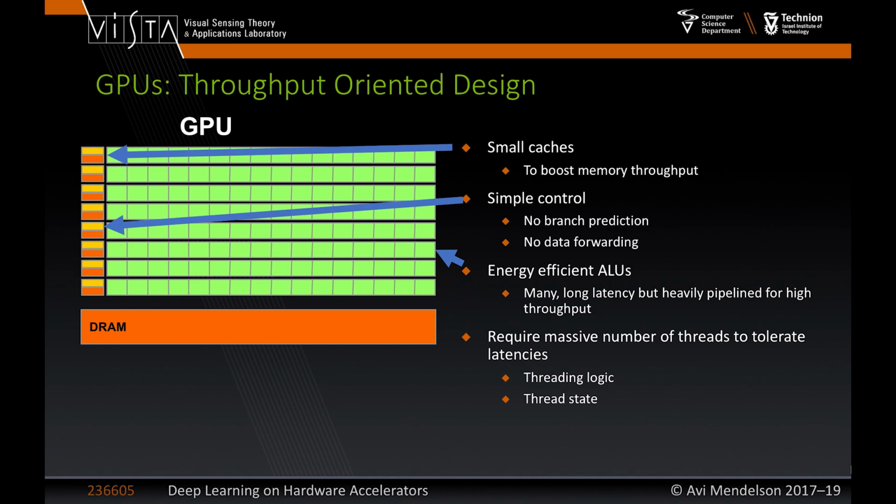But this is marketing. In general, it is true that the amount of logic that you are using in GPUs is much, much more than the amount of logic that you're using in the CPU. More than that, the logic here is used for real computation. It's not used for maintenance or prediction, etc. It's used for real computation. And what do they do about the thermal? Usually they run at a much lower frequency than CPUs in order to compensate.